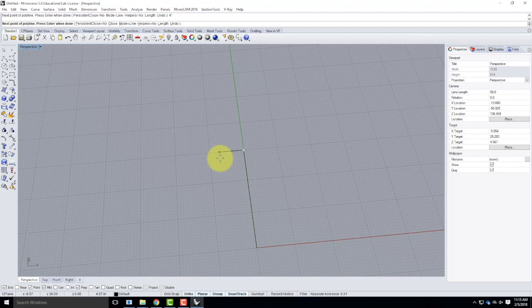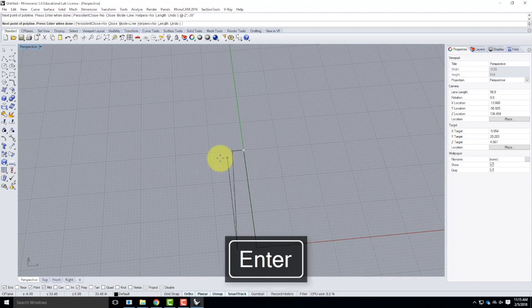Here's a perfect opportunity where, if you use that coordinate system that we talked about on the first day, I can do the next step in one step. So all I would have to do is say at -2 inches, comma, -36 inches. Remember, the at sign is relative to the last point I clicked. I want to go -2 in the x, -36 in the y. I'll hit enter, and there's my sloping line.